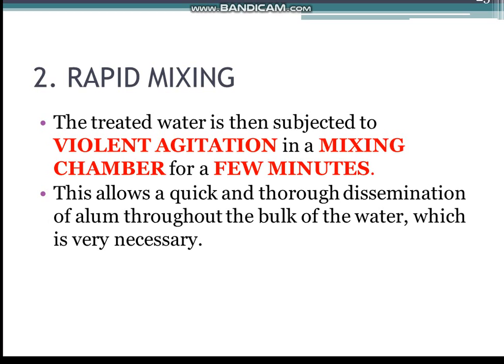Second, rapid mixing. The treated water is then subjected to violent agitation in a mixing chamber for a few minutes. This allows a quick and thorough dissemination of alum throughout the bulk of the water, which is very necessary.